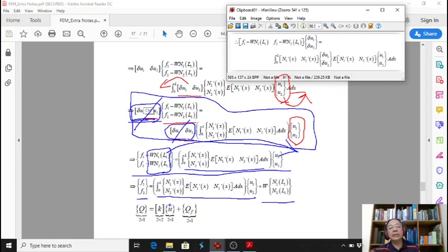And finally, we simplify. The equation now becomes: this is Q, the member force, and this is U, the nodal displacement, U of 2 times 1, and here this is stiffness. So this is the stiffness matrix, or member stiffness matrix K.